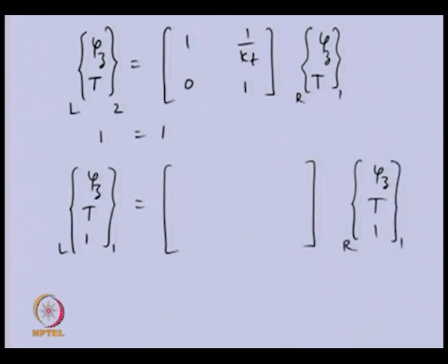Right of disk 1. Now, the first two equations from this give an equation like this, and the identity equation we can insert as 1. So, we can see that the last equation, if we multiply it, we will get 1 is equal to 1. So, this is now the modified state vector left of 2, because this is left of 2.